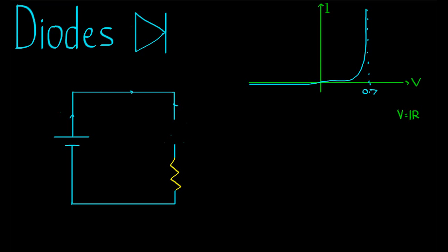that configuration. So looking at a practice question now, with a diode in forward bias. Say I had a 12 volt battery here, and this diode obeyed the rule set out by this graph, and the resistor had a constant resistance of 100 ohms. And the question simply asks how much current is going through the diode. The first thing to note is that these two components are in series, therefore the amount of current going through the diode is the same as the amount of current going through the resistor here.